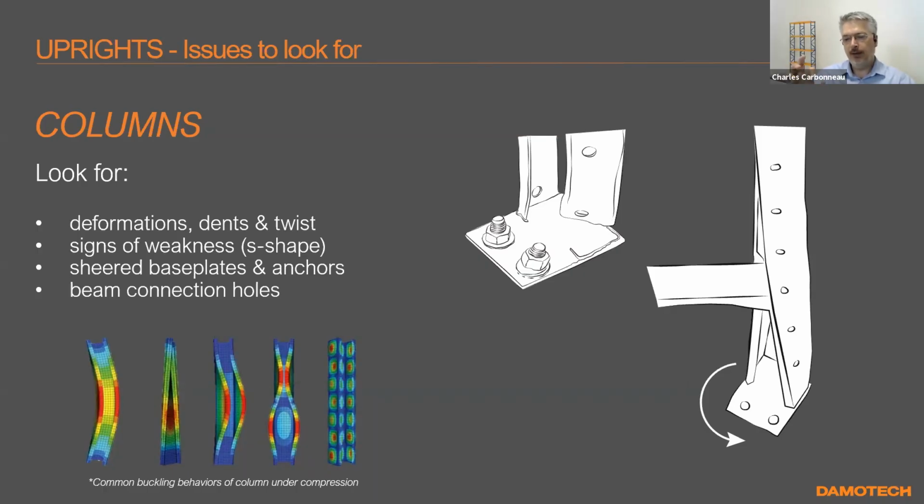Usually they make their beam connectors compatible with different columns so that you can mix, but there is some risk in terms of lateral stability. Only the beams are giving you this lateral stability when you look down the aisle. And if the connectors are not tight and specific to that type of column, you can get in trouble in terms of lateral stability.